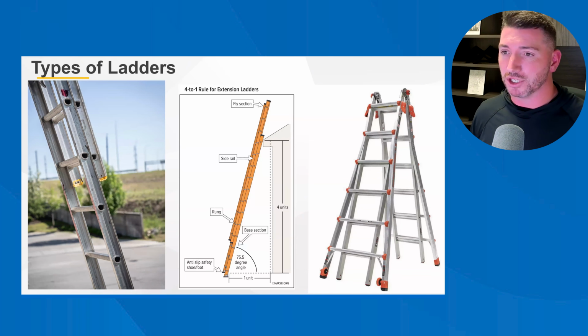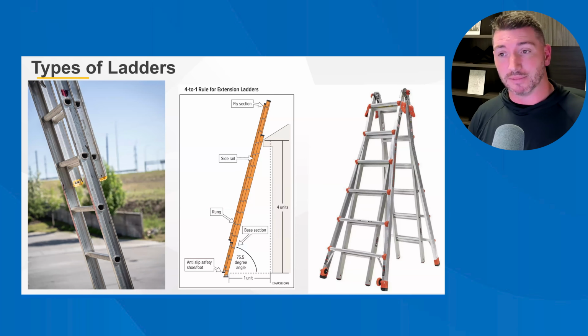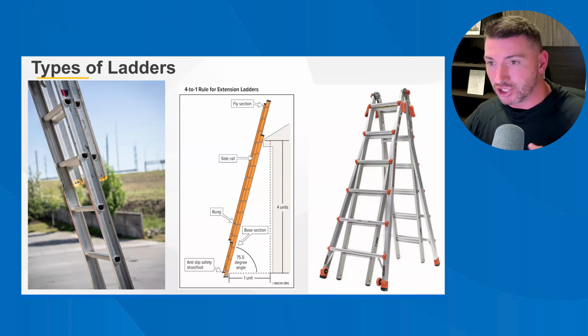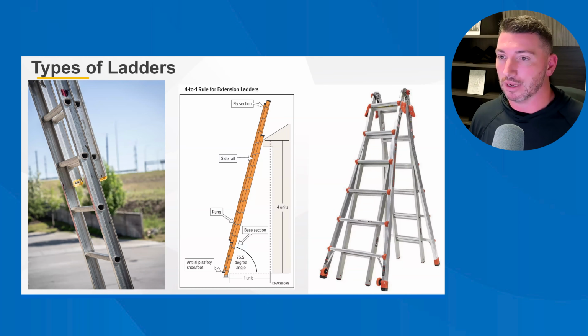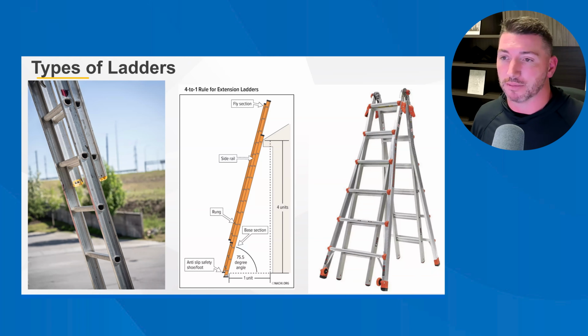You just have to remember with a bungee cord, the goal of tying off your ladder is twofold. One, it stops your ladder from blowing off the roof when there's a high wind. But two, if you end up taking a bit of a slide because it's a slick shingle, you want to be able to slide down to that ladder within reason and not have it stretch off the gutter with the bungee cord, because then you're going to fall in between the ladder and the house, and that's no fun. So I would recommend some kind of a Velcro strap, something that has a bit more solidness to it.